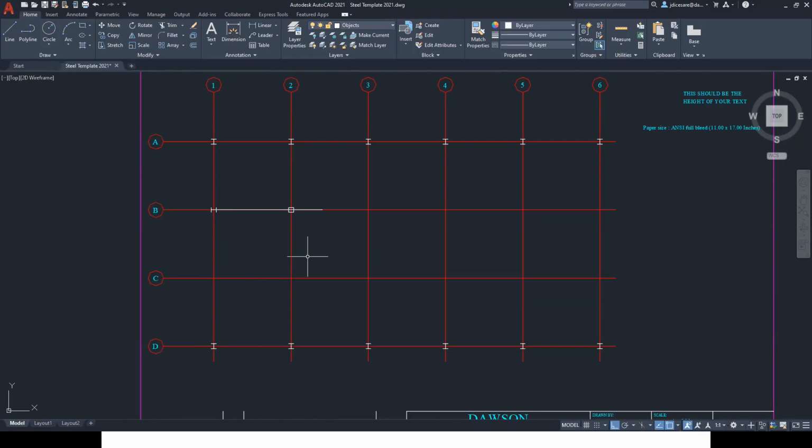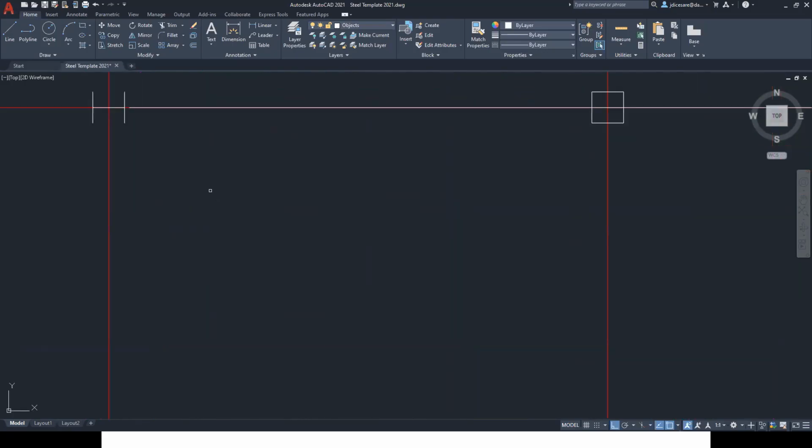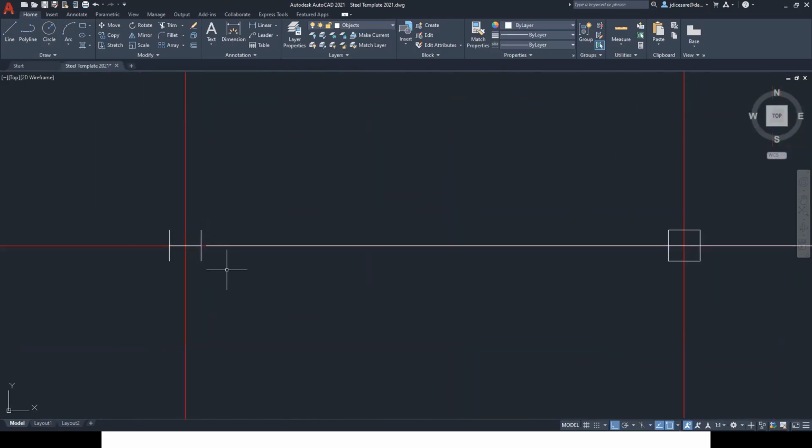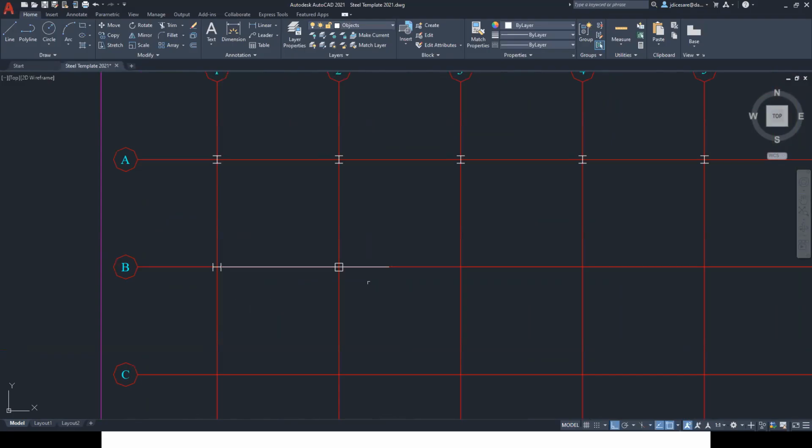But in reality, when it comes to structural steel, the column sizes, like for example, this represents a beam. Do I show the actual beam size? You understand? Structural steel drawings are mostly like stick drawings. They're all sticks. Line here, line there, line there. But there are certain graphic rules, like here, this line doesn't touch, and this goes over it. So that means the column is below the beam here. These are all little things that are significant in structural steel.